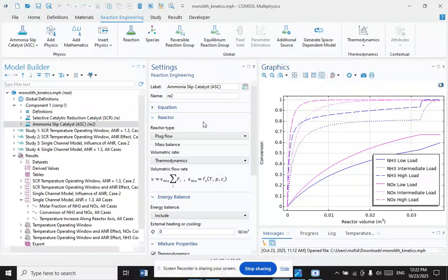The competing chemical reactions raise the issue of optimal dosing of NH3 to handle the reduction process in the first bed. Stoichiometry suggests a 1-to-1 ratio of NH3 to NO as a lower limit for the standard SCR reaction.